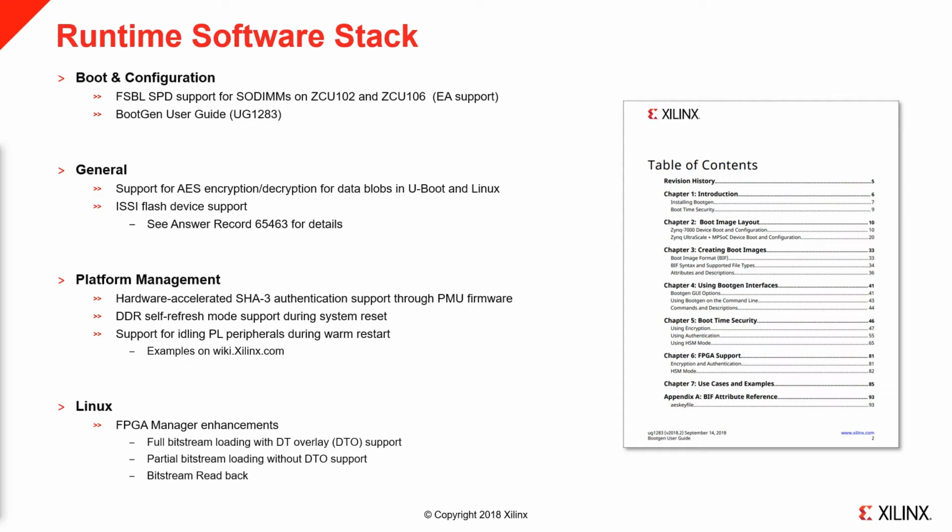In addition, PMU firmware now supports some new features that will make performing a warm restart easier. First, it now supports placing memories into DDR self-refresh mode when doing warm restart. This allows the system to reuse existing memory configurations when restarting rather than retraining the memory and losing data. We've also added support for idling peripherals located in the programmable logic during warm restart events. For more details on the use models and examples, please go to the Xilinx wiki at wiki.xilinx.com.